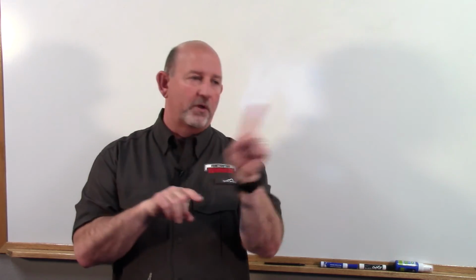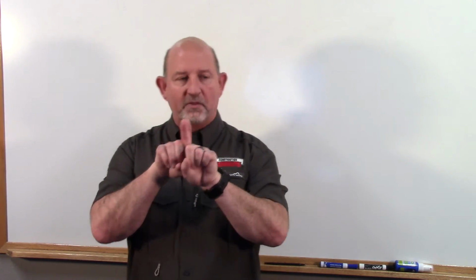If I turn on all the hot and all the cold, I'm going to get 1 WSFU of warm. So do you agree that lavatory is never going to demand more than 1 WSFU, whether it's hot, cold, or warm? That's why we don't have to increase the building supply line to accommodate the water heater, and why we don't have to increase the branch lines after that to include the water heater, because we've already calculated that lav as 1 hot, 1 cold, 1 warm. It's going to all be the same.